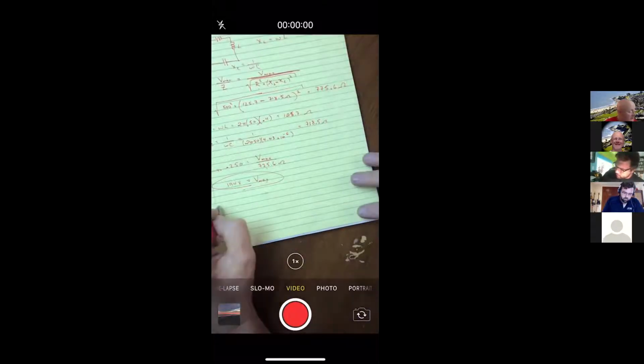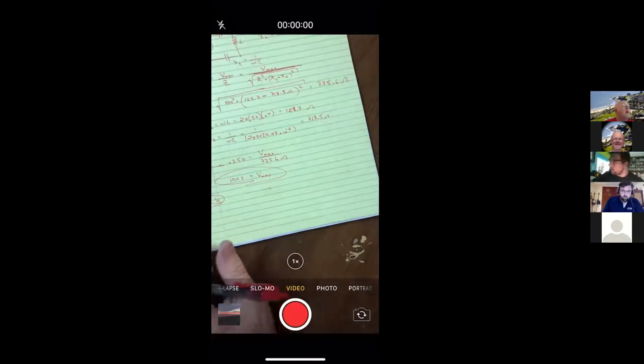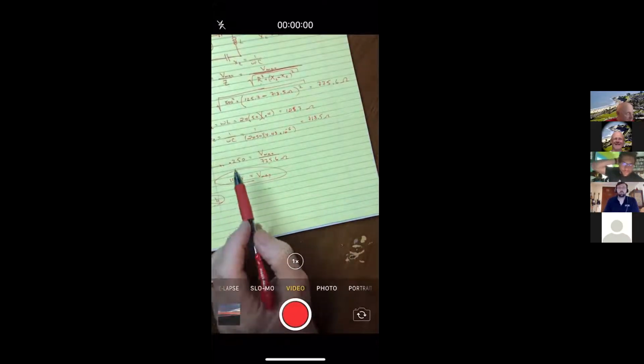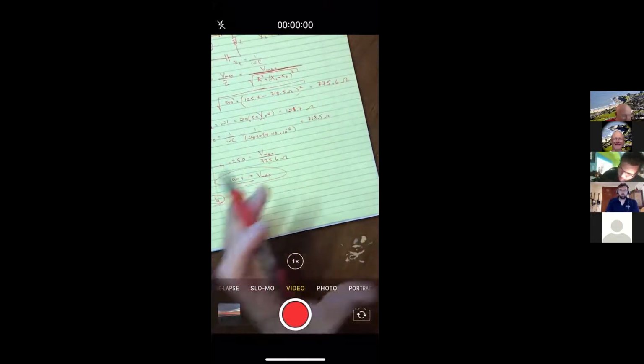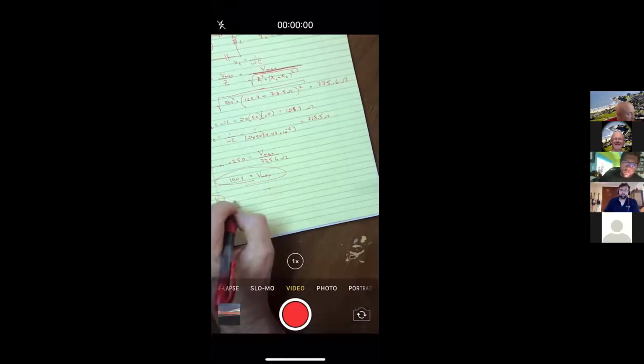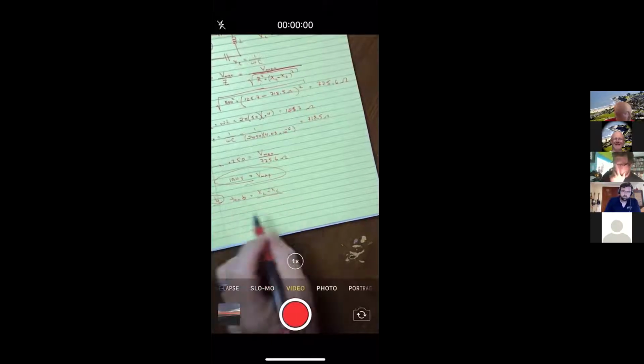Now there's a part B to this. Part B says, determine the phase angle by which the current leads or lags the applied voltage. All right, so another interesting effect, very different than the resistors, is that the current and voltage aren't necessarily in phase. They don't happen at the same time. And so the angle that one leads the other was given by the difference in these two.